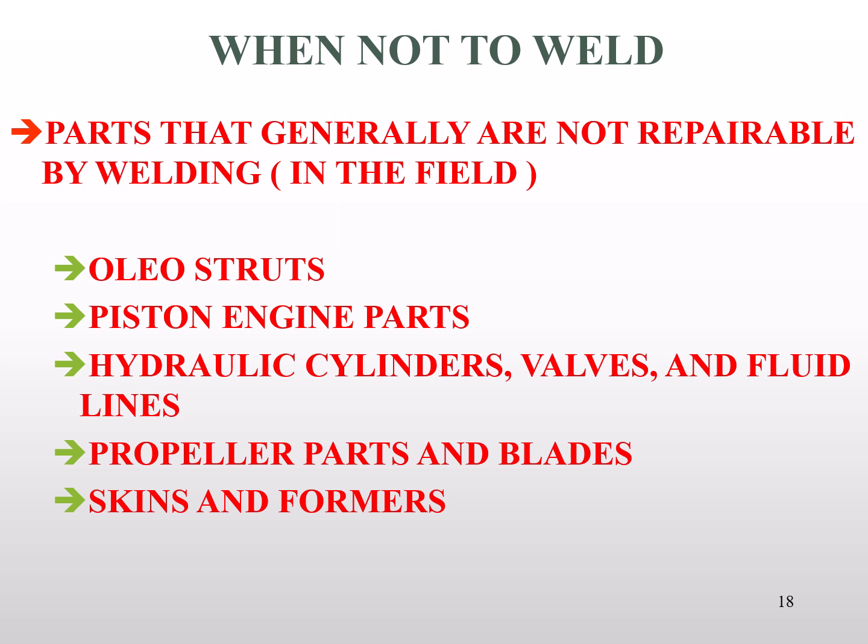We could never weld on any portion of a propeller. As a matter of fact, mechanics are strictly limited in what we can do, even under normal maintenance to propellers. And any type of aluminum skin or former are not eligible to be repaired by a welding process. The majority of material used, aluminum sheet, in structural applications has gone through a heat treatment process. If we weld that material, we'll destroy its strength.